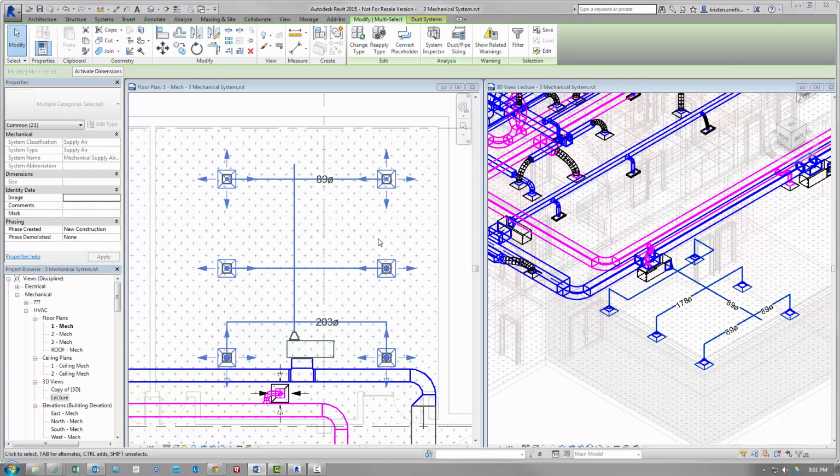Next, I examine the duct sizes and identify a problem. The main duct is smaller than the branches. The system is not closed and will require an end cap as well as some intermediate transitions along the main run to balance the system correctly. This will create the most efficient HVAC system.